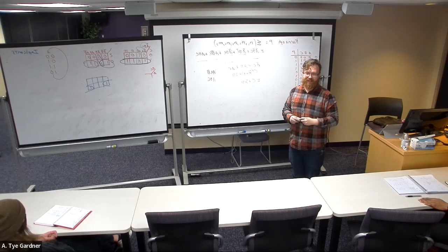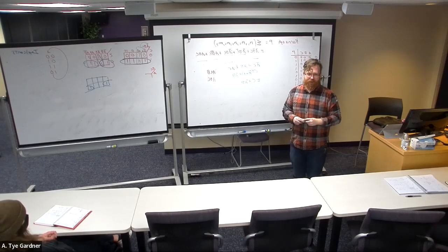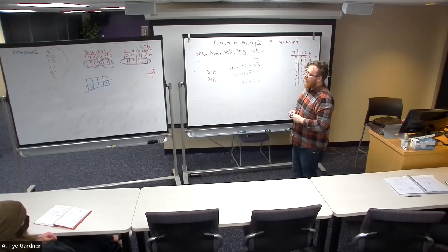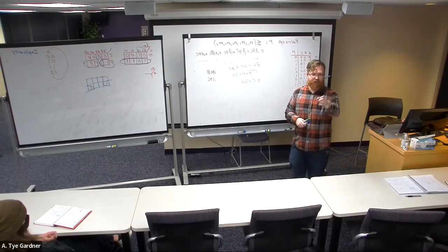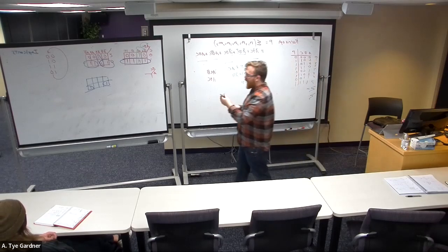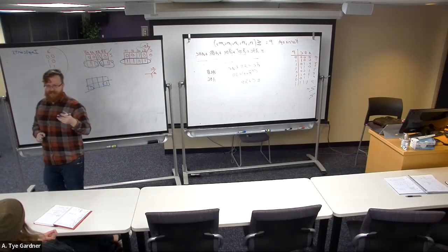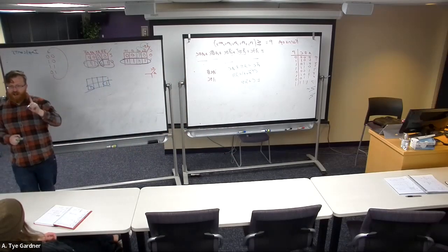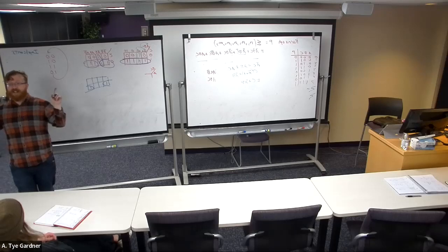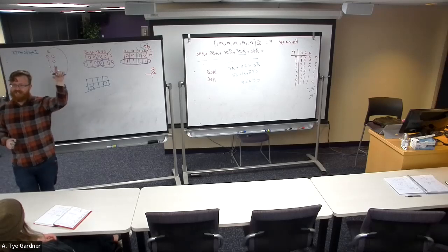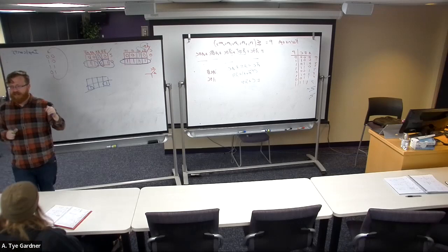Is there a limit to how many ones you can circle at a time? There is a rule to the number of circles that you can do, but not a limit. The rule, and this is a great time to introduce that, is you can circle a number of ones so long as they are all logically adjacent, meaning no diagonals, no weird curvy angles. It basically has to be squares and rectangles.